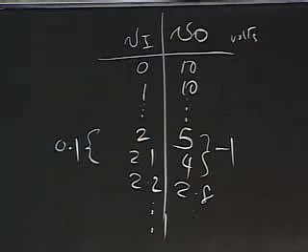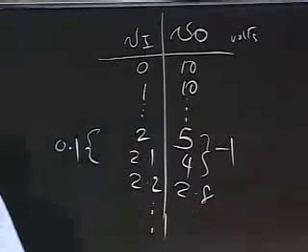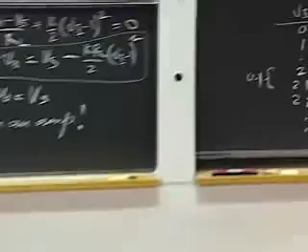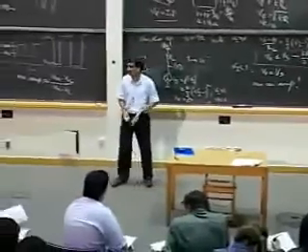So input went up by 0.1 volts. My output kerplunked down by 1 whole volt. So a small change here resulted in a bigger change there, and that's the amplification that I am claiming here. So let me show you a little demo of a small device that I built involving such a dependent source.